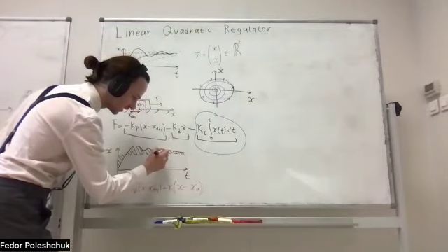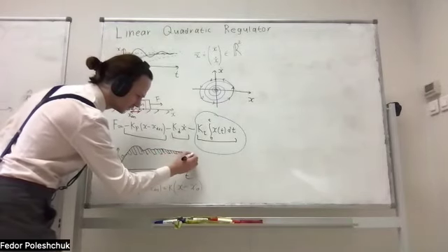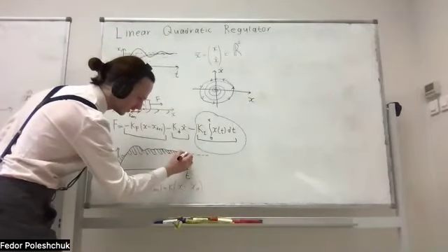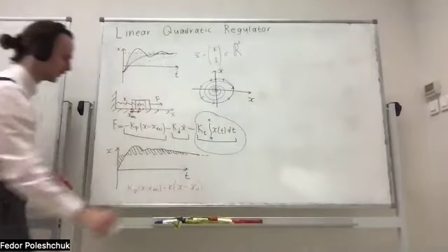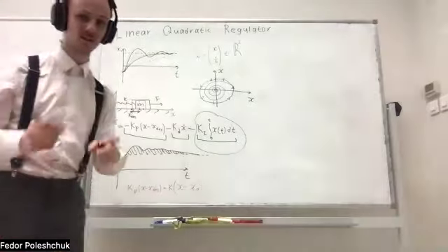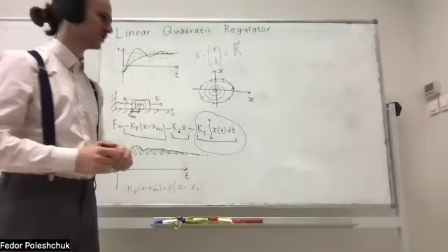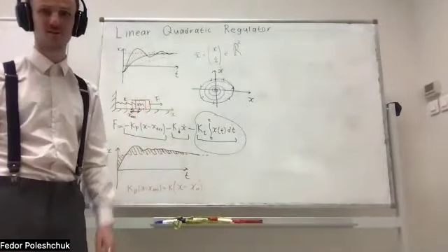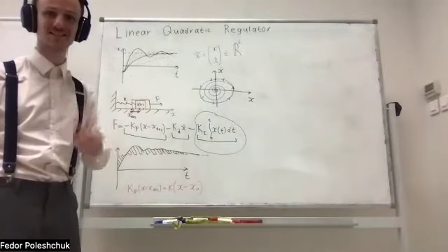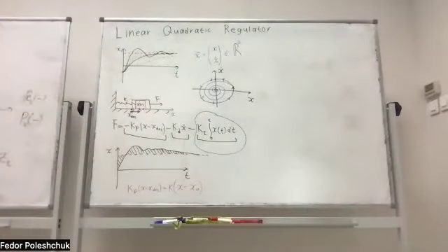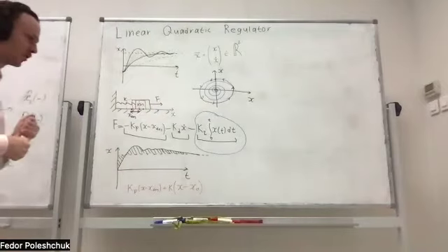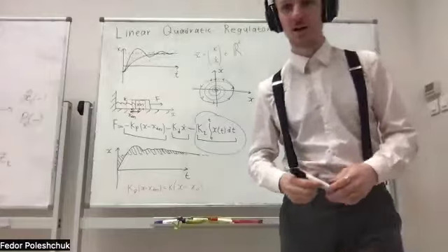So it's asymptotic convergence, really. We will never approach the desired position exactly, but we really don't care if we have approached it up to a millimeter or something. We're already there. We can easily be satisfied with that. So this is the concept of PID control.